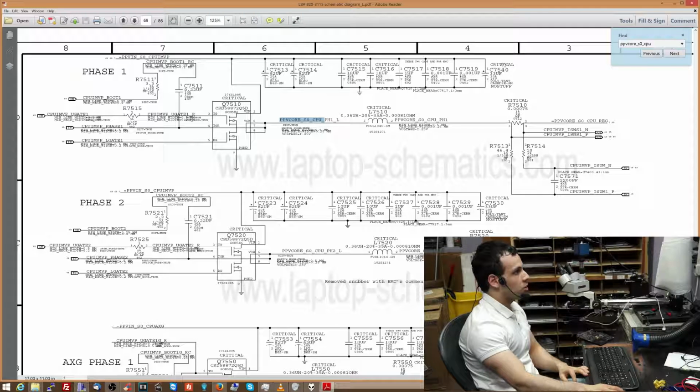So over here you're going to have the 12 volt rail of the computer. Up here you have a 12 volt rail, and that's going into, I believe, the source of this dual MOSFET. I think this is like 2 MOSFETs in one package. So that's going to be going over here. Now, what that's going to be doing is opening based on the signal at the gate over here. And on the other side, you have a MOSFET over here that's sending that same power to ground. So it's pretty much giving it a path of where to go.